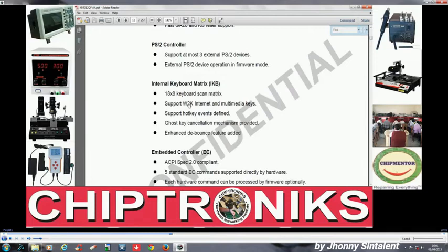But in a laptop keyboard, if you try to dismantle it, you won't find any IC present in that laptop keyboard. This is because both the keyboard encoder and keyboard controller are present inside the IO controller, whereas in a desktop keyboard, the keyboard encoder is present inside the keyboard and the keyboard controller is elsewhere.